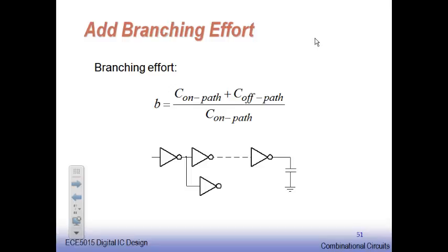Now in this process, my charging the nodes would be the current what I give for my one path, another path, and second path and a third path. For each of the paths, based on their own gate capacitances, I will have to be sending current for charging. So in such a case, I have got to consider the branching effort also.